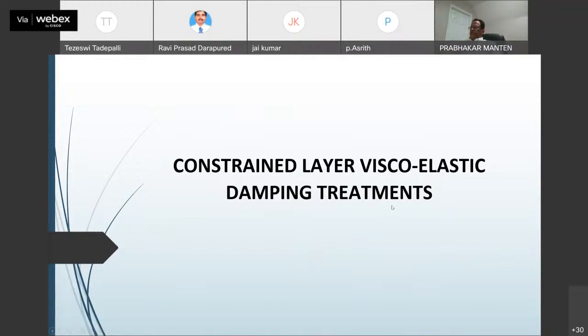Now I come to some of the type of work I do a lot, in trying to find out how to reduce vibrations on structures, and improve some using so-called viscoelastic damping treatments. Viscoelastic materials can be used as dampers, freely applied. Most of this is done quite often around your engine blocks, where they put thick layers of it freely, unconstrained.